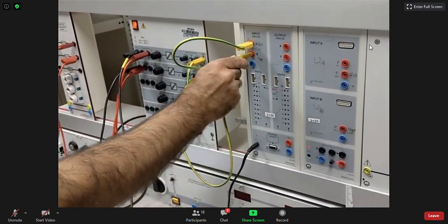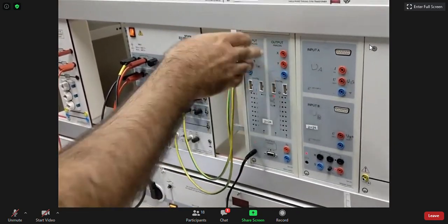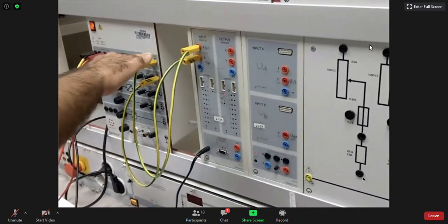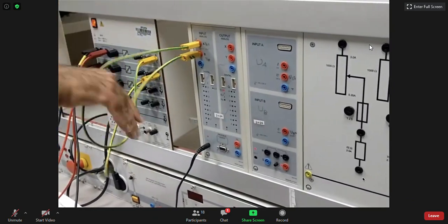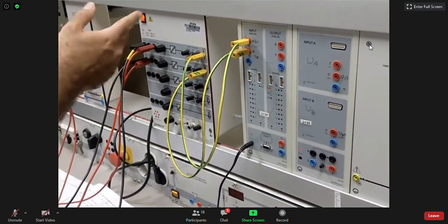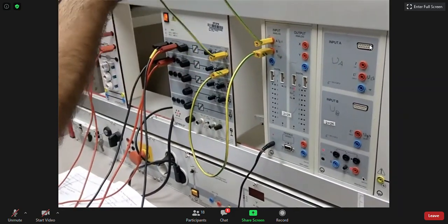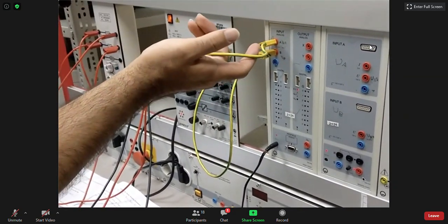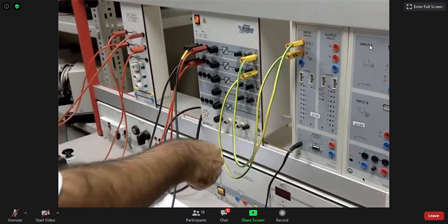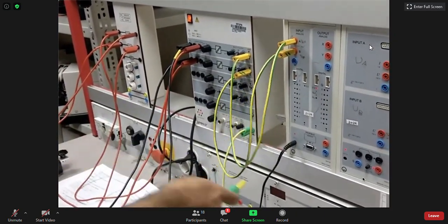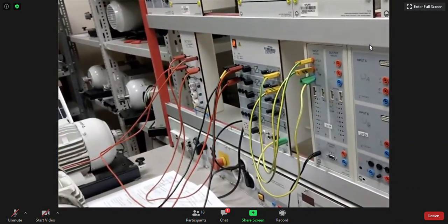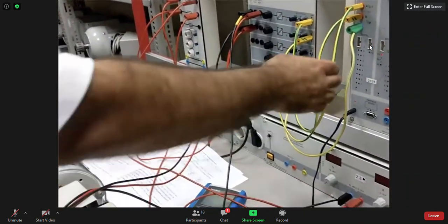How do we know this is UA1, UB1? You remember it, and we can see it in the CASSY Lab software very soon. So this is 1, this is 2. Any voltage measurement should be referred to some reference. You should use 2 terminals. This voltage is with respect to what? All these channels are with respect to this neutral. So this is the common neutral for all channels. This neutral will go here, so this will represent all of them. Okay? So this is for voltage.